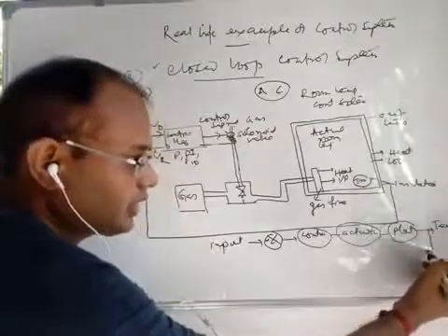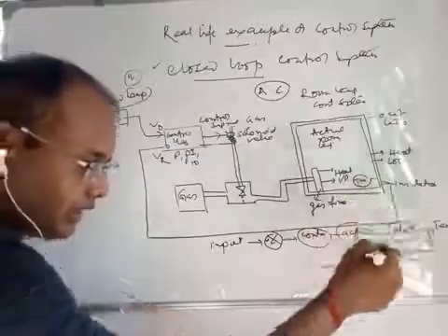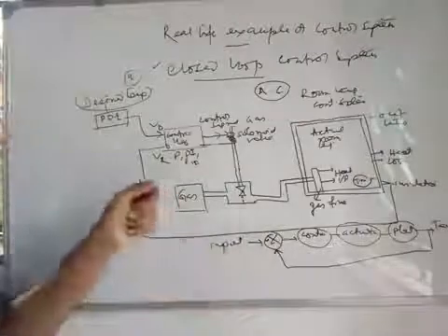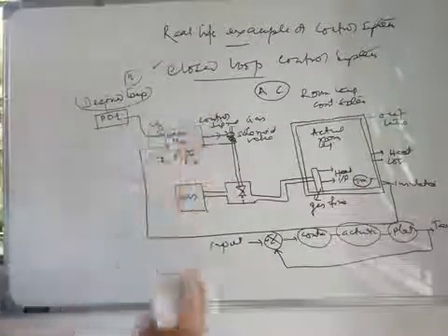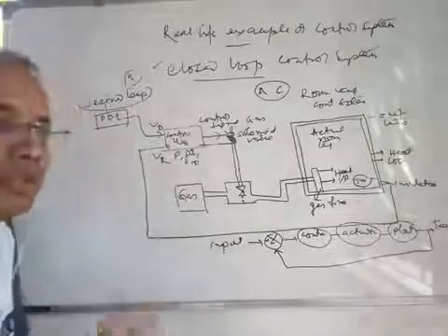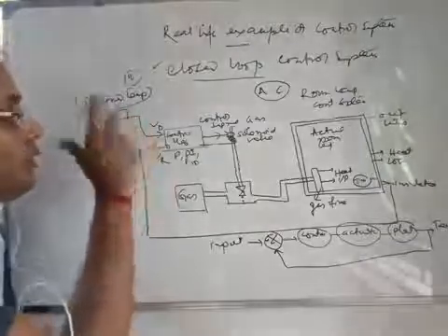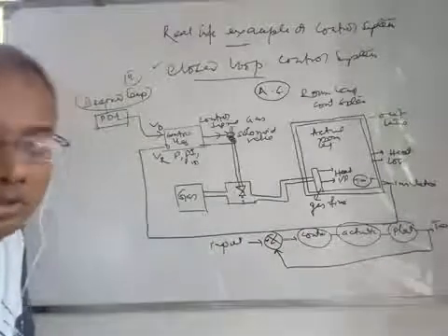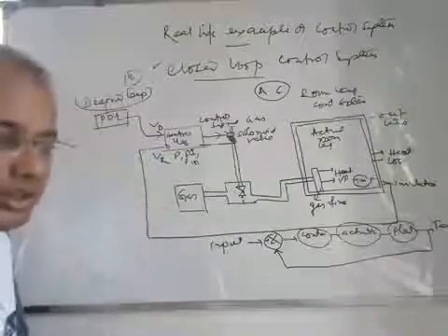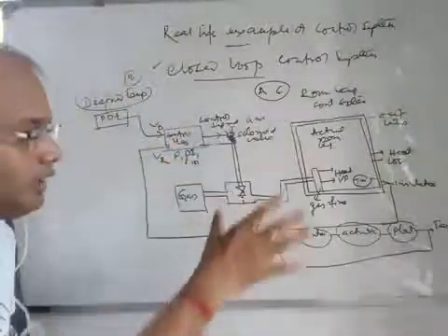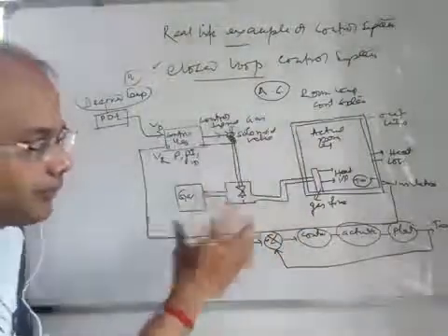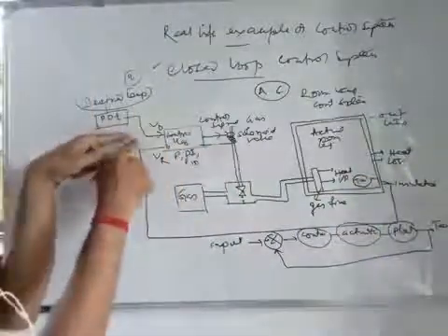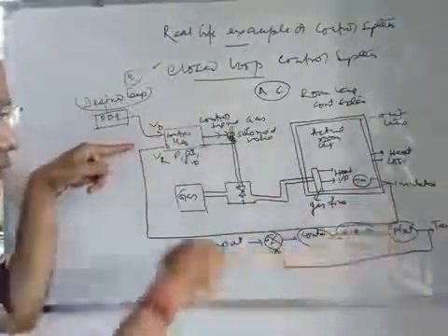Now this temperature is sensed by another temperature sensor, that is a thermometer, and this gives you some voltage here. And as with the PID controller, all the controller types available in the market normally work on voltage. So every kind of sensor output, maybe level, temperature, flow, or pressure, must be converted to voltage by using sufficient conversion instruments. So this is a closed loop system, because at every instant of time, from the input side, you are getting the information of the output.